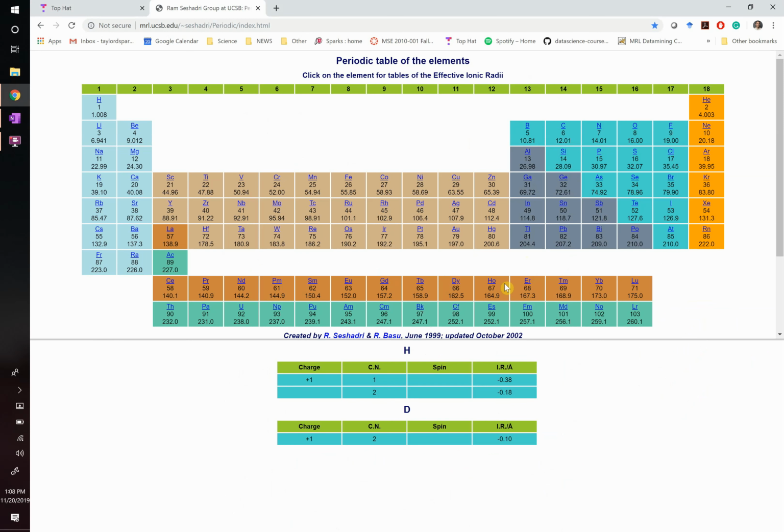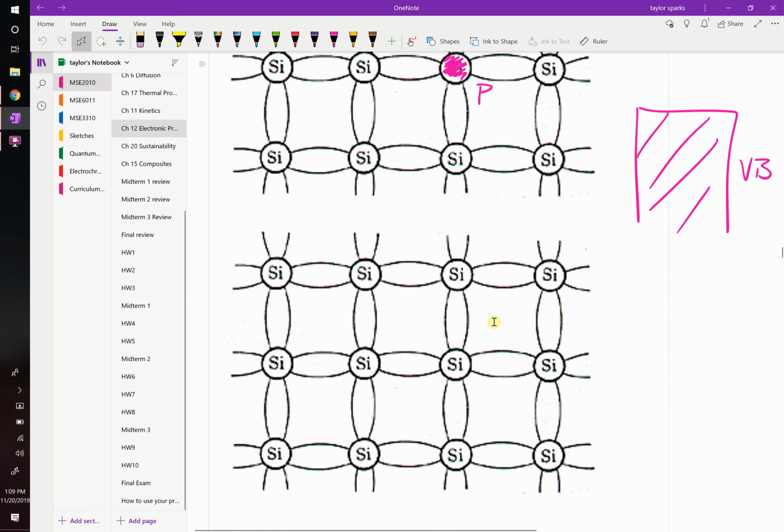So like, yeah, we had silicon right here, which was group 4. Adding something to the right gives it an extra electron. To P-type dope it, we want to give it an extra missing spot for an electron. So something to the left, like boron, aluminum, gallium, indium. Group 3 elements are going to P-type dope it. So in our lattice, they're now going to look like this.